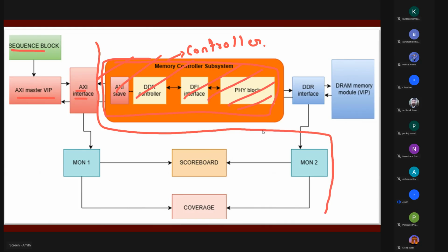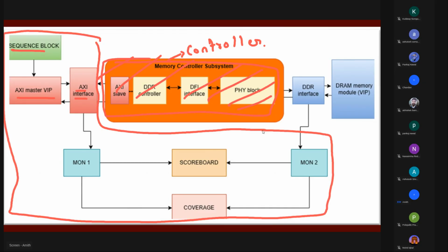Using this UVM setup, we are going to verify the protocol. How? We connect one monitor here and one monitor from here. We take the reference model of the controller inside the scoreboard, and generate the exact same thing which is going in and coming out, inside the scoreboard, taking the reference from this.